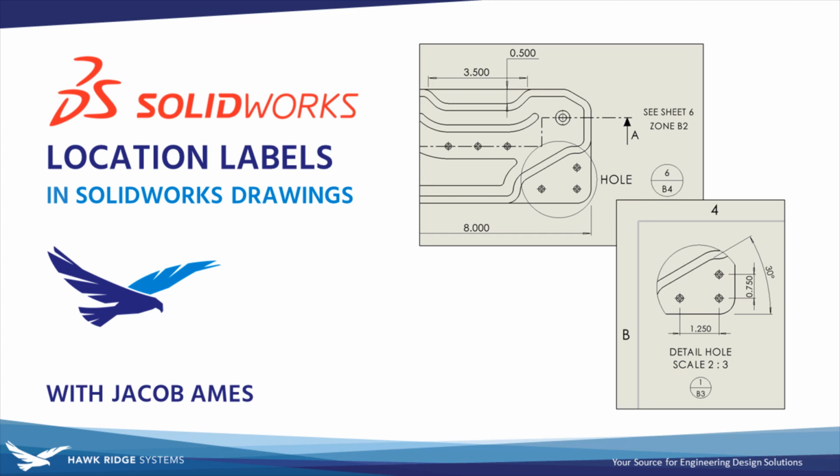This is Jacob Ames, Senior Applications Engineer, and if you found yourself spending too much time digging through drawing sheets looking for specific views, then this video is for you. Today we'll be covering location labels in SOLIDWORKS drawings, which allow you to quickly find section, detail, or auxiliary views right from their parent view, or vice versa.